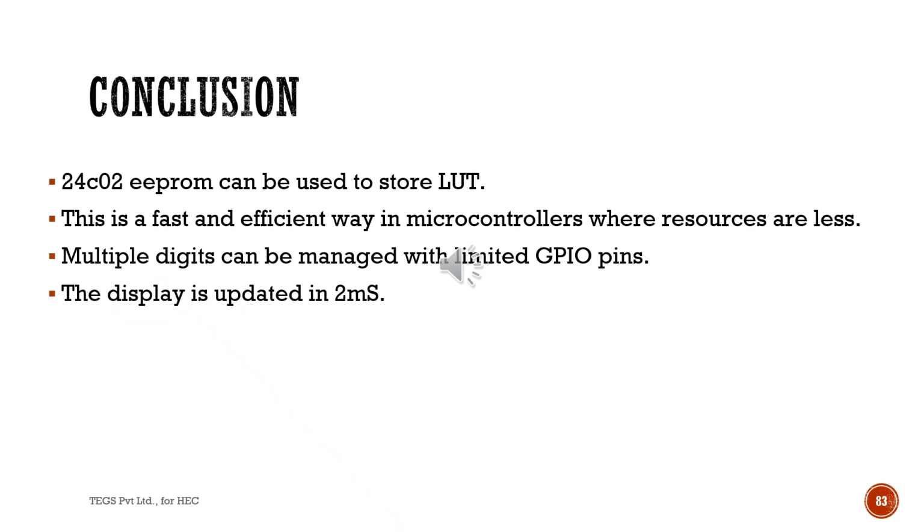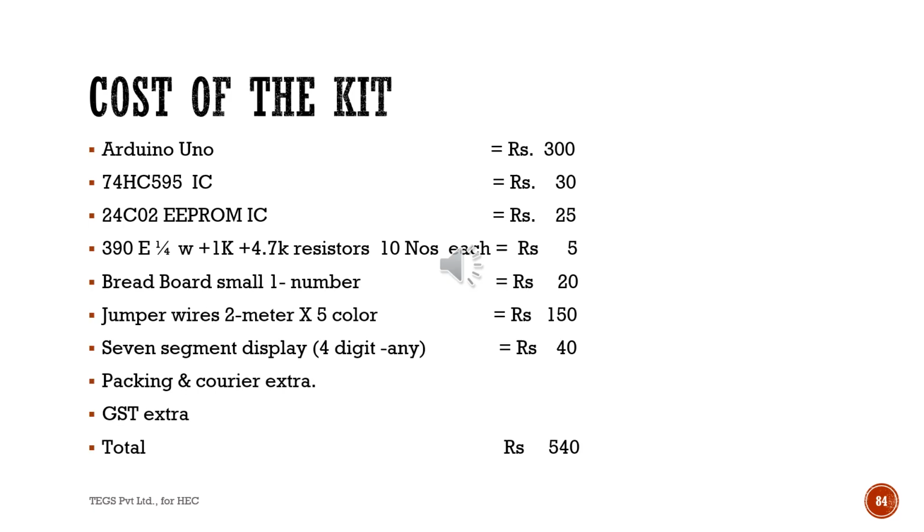Conclusion. The 24C02 EEPROM can be used to store the lookup table. This is a fast and efficient way in microcontrollers where resources are less. Multiple digits can be managed with limited GPIO pins. The display is updated every 2 milliseconds.